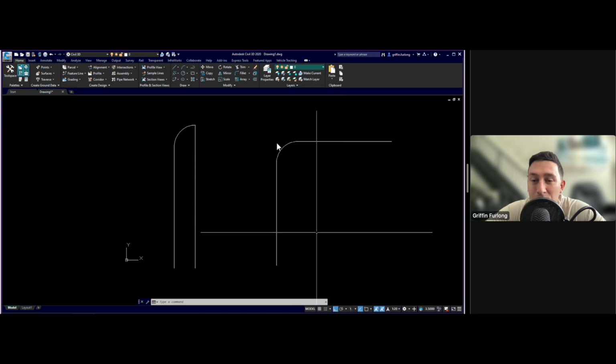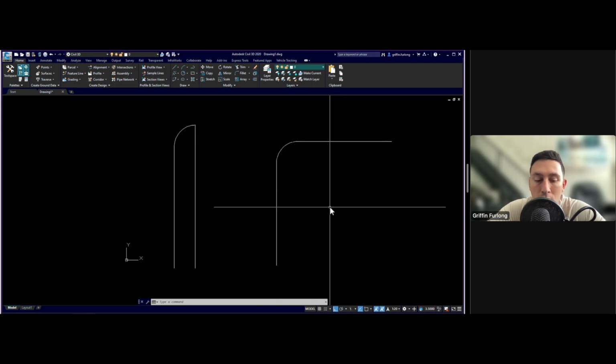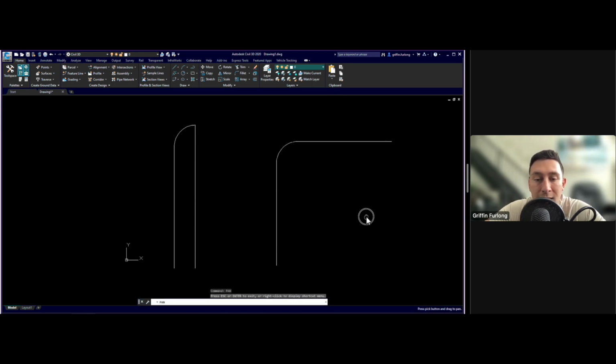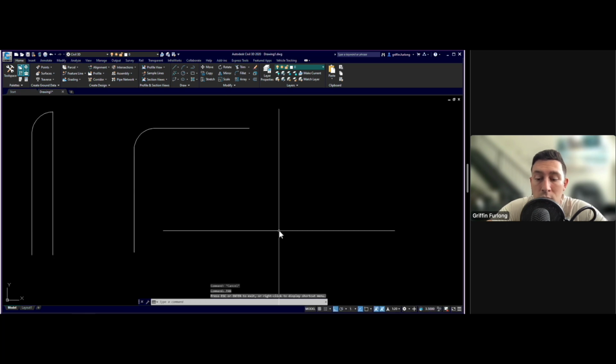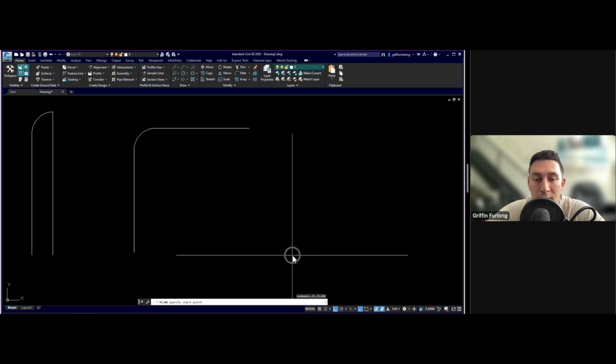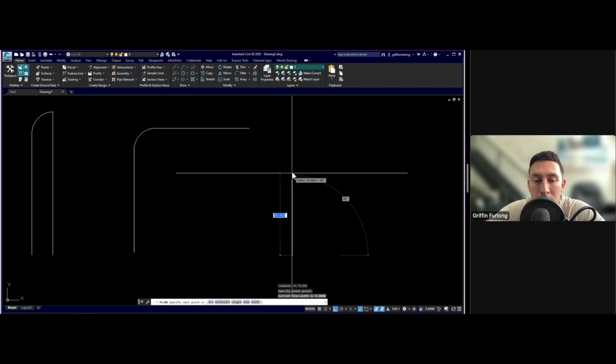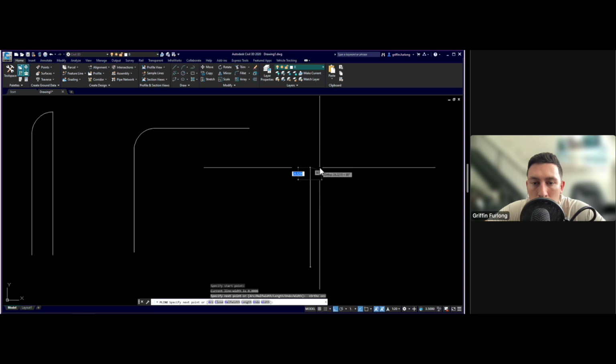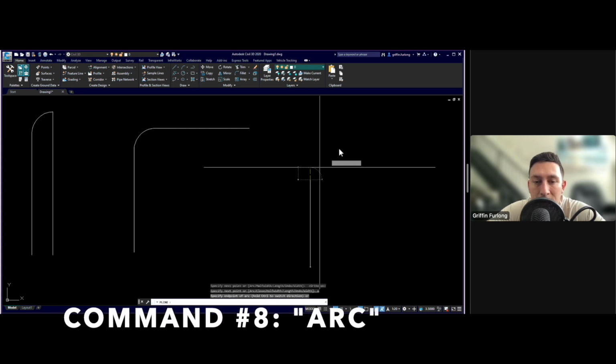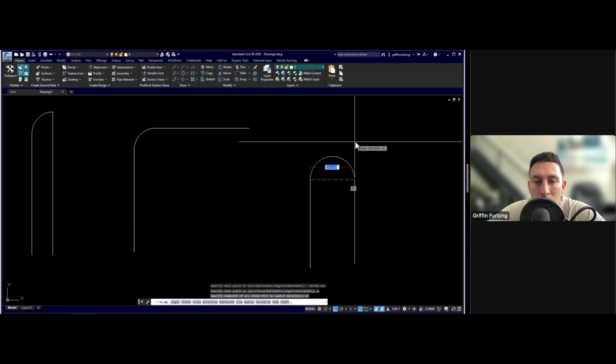I'm going to show you a third way of how to generate this curve because there are a million different ways to draft, and I just want to show you some drafting tips. So I'm going to continue by drawing another polyline. But once I reach this polyline, I'm going to do a point of control right there. And then notice how polyline has a setting down there called arc. I'm going to press A and then enter, and then watch it now form an arc.